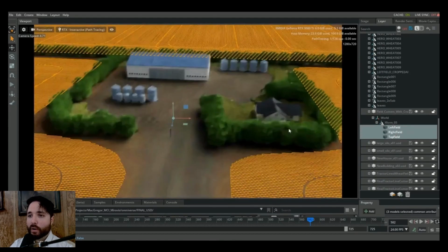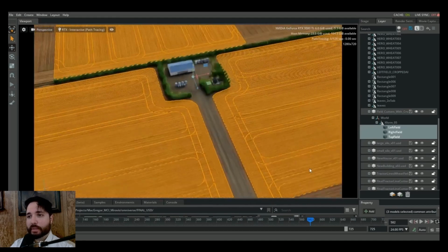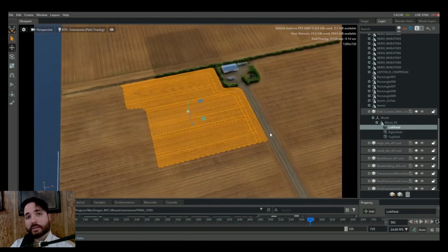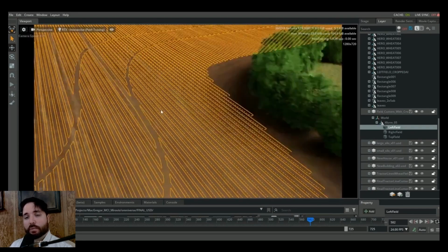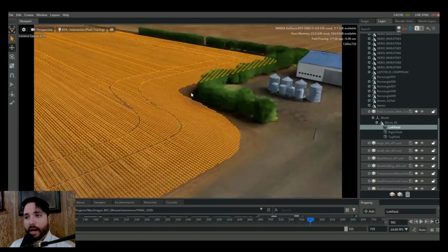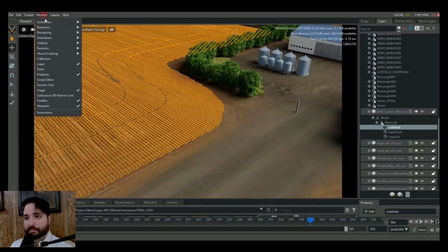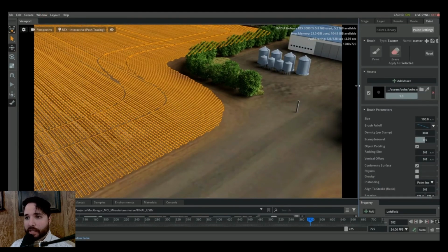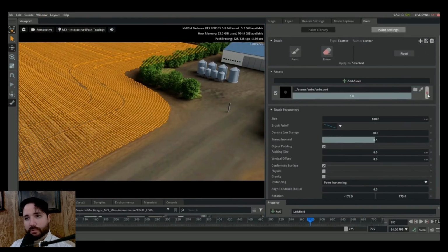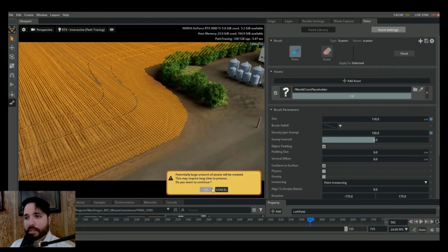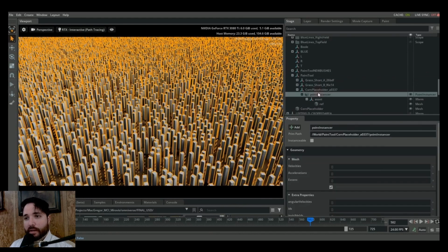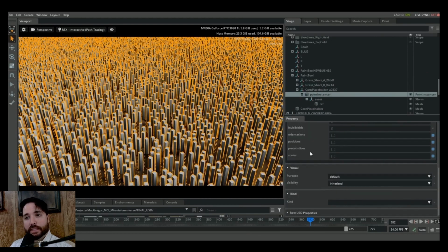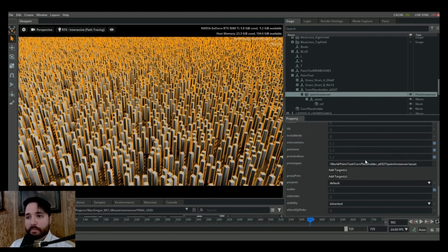In my case, I wanted to animate my instances of the plants growing and also have them react to the wind. But I also needed to have a lot of control over the placement because the client wanted to show tractor lines and closely mimic the real process. So in order to do this, I made these large-scale objects in 3ds Max for the wheat rows so that when I flooded my wheat plants to the scene, they'd be generated in a very specific way. To generate large amounts of instances quickly, I used a cube that approximately matched the volume and dimensions of my wheat plant.